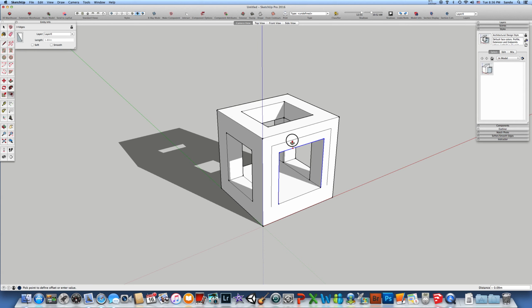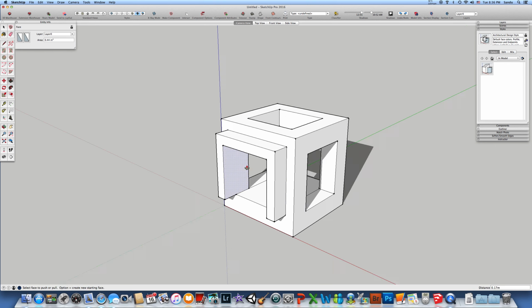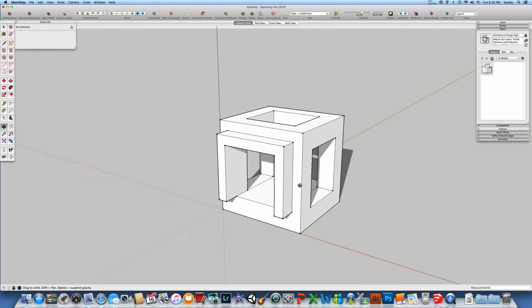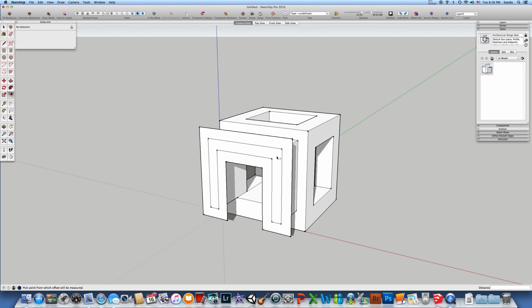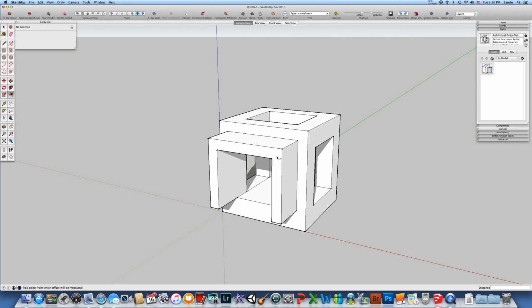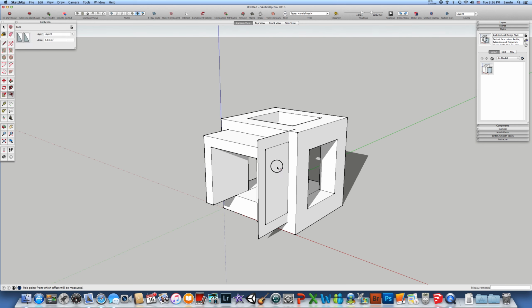And here it is. Click on L to build a line, and you always need to have the surface closed. When you have an area closed, notice also the line becomes a little bit shorter. And again, with push-pull, you can move the area outside, and you can start building whatever you need. Again, double click on this one, and usually it's repeating the operation which you just did. So I think this is good to know. On this one, again, double click is going to repeat the operation.